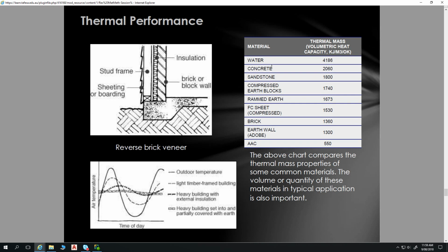So what you might do with your western wall there, because this is your actual structure here, you might decide not to have that thermal mass on that western wall, and maybe you double stud. So two studs and then more insulation on that western wall where that insulation is required. That might probably even be a better approach.